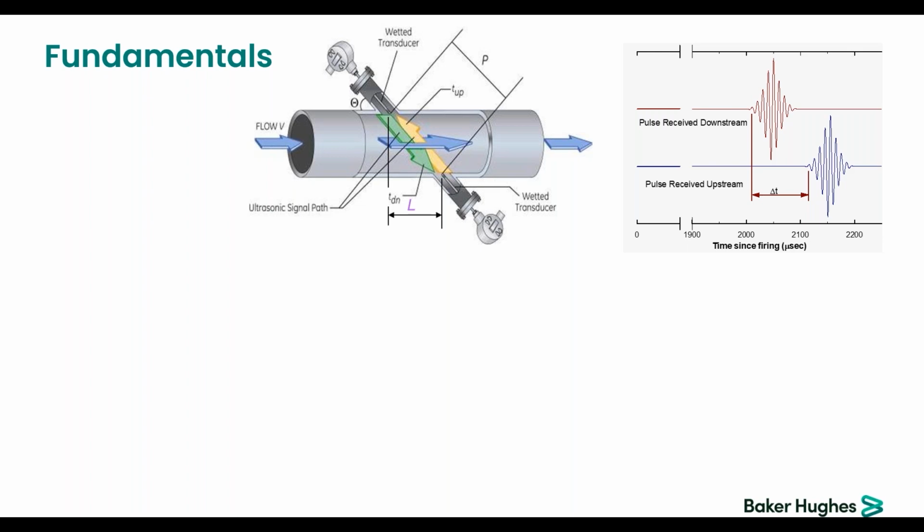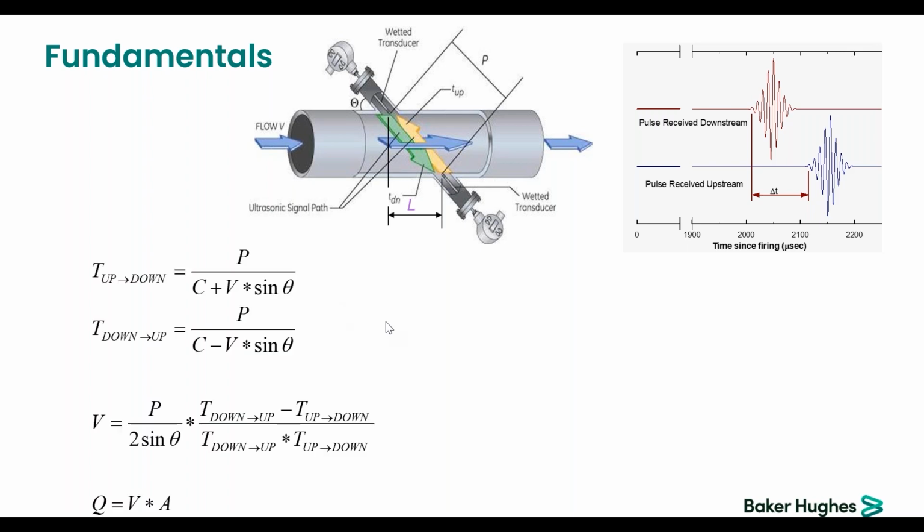measurement. Because when I need to go from the upstream transducer to the downstream transducer, if I go with the flow, like the green arrow you have there, it will be accelerated, while in the reverse direction, it will be decelerated. And this time difference is directly proportional to the velocity of the fluid. And it doesn't matter what fluid it is. It can be steam, it can be air, it can be water, it can be anything, okay?